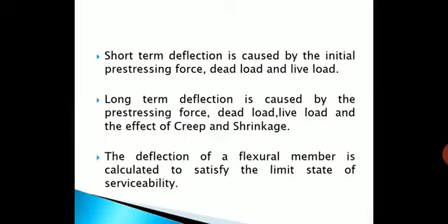Short-term deflection is caused by the initial pre-stressing force, dead loads, and live loads, whereas long-term deflection is caused by the pre-stressing force, dead loads, live loads, and along with this the effects of creep and shrinkage.